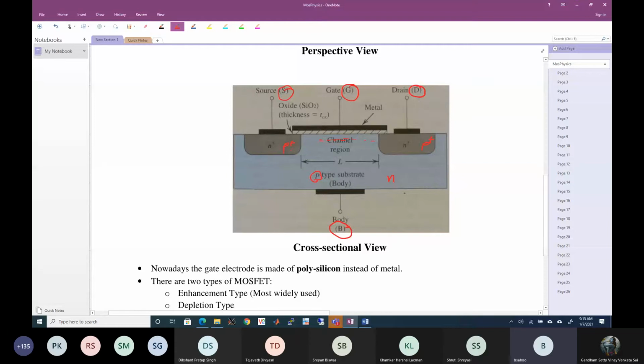Usually, when you buy a silicon substrate, you have one substrate which is typically P type. On that same substrate, you have to fabricate a PMOS as well. So let's extend the substrate a little more over this side. Now I want to fabricate a PMOS over here. For a PMOS, the body has to be N type, but the substrate is P type. So what we do is we make something called an N well. That becomes the substrate for the PMOS, and then we make the source P plus over here, and the drain P plus over here.